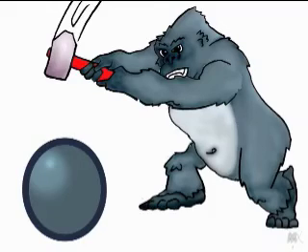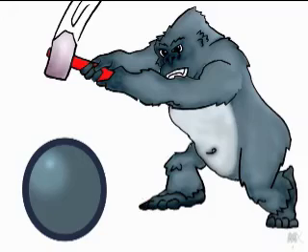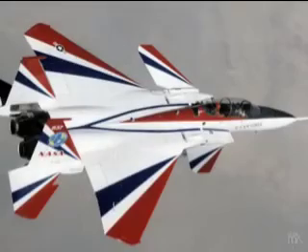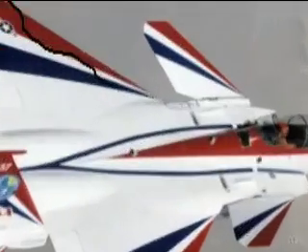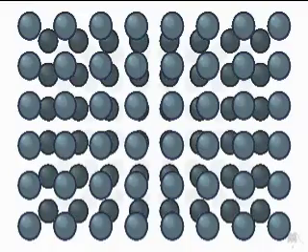CSR particles toughen a polymeric matrix in multiple ways. The core acts to dissipate the energy of an impact. This cavitation theory of impact modification describes the CSR core deforming, effectively mitigating the energy of the blow. CSR particles themselves also act as crack terminators. Cracks or fissures that start by any mechanism are stopped when they encounter a CSR particle. Optimizing the size and dispersion of CSR particles in a polymeric matrix increases the probability of the crack meeting a terminator.